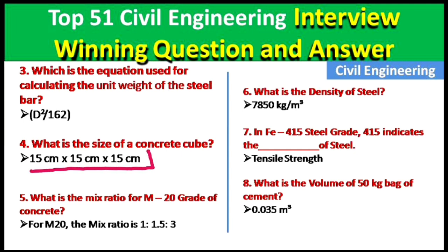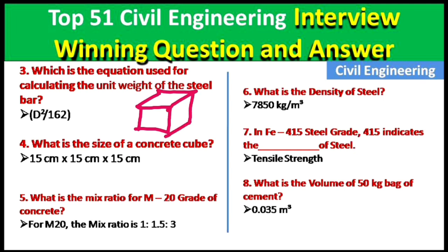Okay, now point number 4 is: what is the size of the concrete cube? Guys, this is the size of the concrete cube which is used to measure the compressive strength of the concrete. When we prepare concrete, then we have to prepare several cubes and test them in the lab. So how much should its length, width and height be? 15 centimeter, 15 centimeter and 15 centimeter.